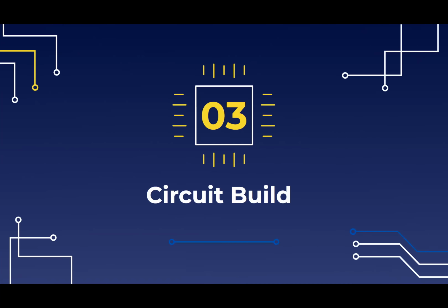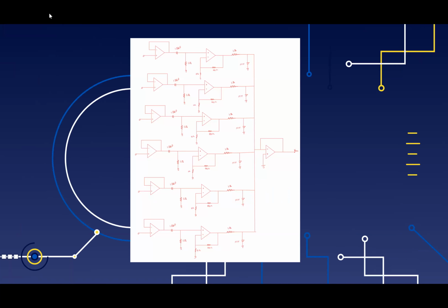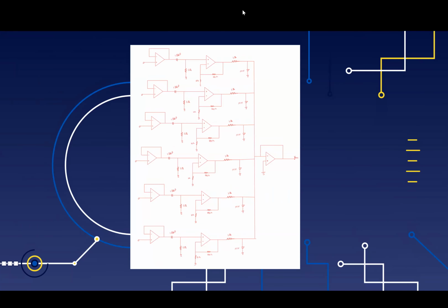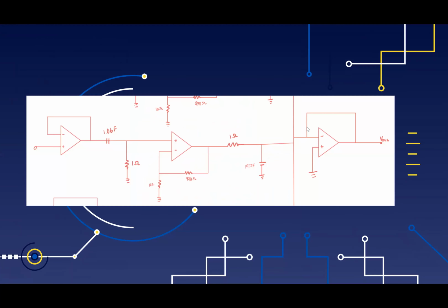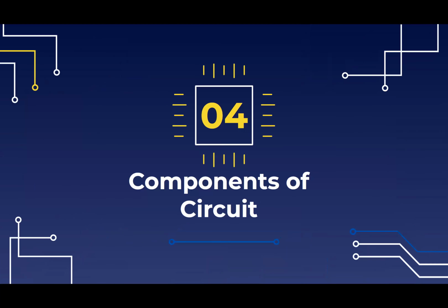So now we will go into how our circuit is built. Using all of this information, we developed a circuit diagram. Since we have 6 to 8 sensors that get placed on the stomach, they all have to get inputted in separately. They then all follow the same voltage follower, op amp, and band pass filter before getting summed up and outputted. To make this a little easier to follow, we isolated one single pathway to break down the components of the circuit and to make the design a little easier to see. This is that right there.